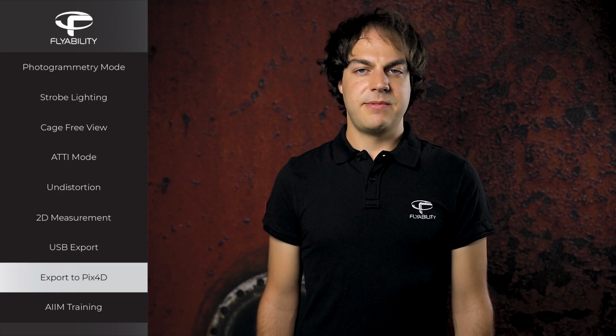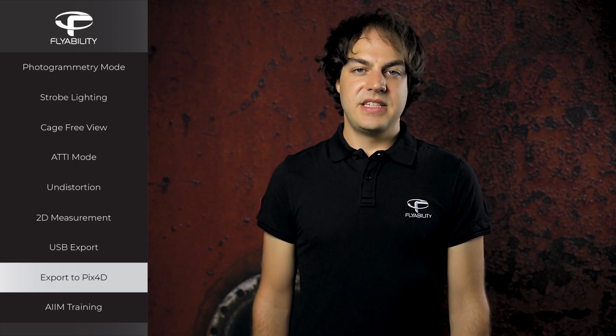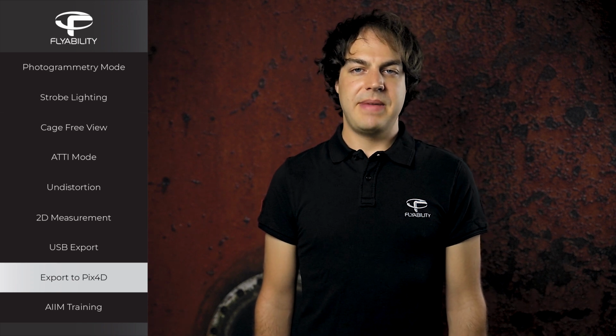Photogrammetry software can be tweaked with many parameters. We have experimented in different assets to find the optimal values to be used in Pix4D. Inspector offers you the optimal parameters in the form of a Pix4D template file, which you can import into Pix4D Mapper and then use during the model creation.